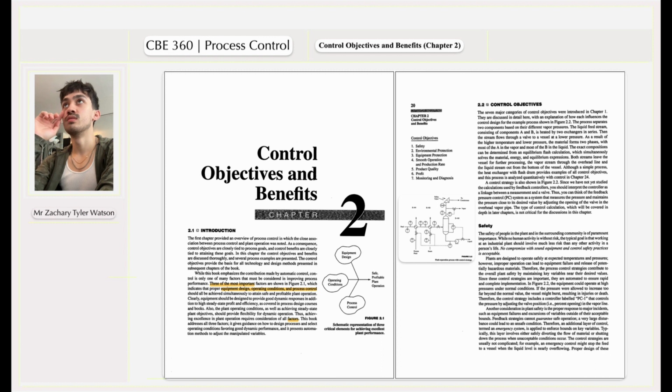And notice that if the safety valve is closed, vapor will just be trapped in the length of the pipe, just below the safety valve opening. But you also have to account for a pressure gradient. If the pressure is causing the flow to leave through the exiting pipe, the liquid just before the inlet of the safety valve would be caused to move out just because the flow is exiting. And materials like to move together. That's really due to pressure gradients.